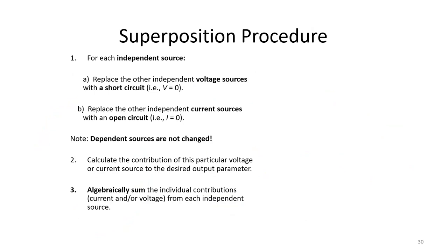Remember that the superposition procedure is actually pretty straightforward. And this is also a very convenient exam question because solving superposition problems often requires use of other tools like voltage division, node analysis, and our other DC circuit tools. So remember, what you want to do with superposition is draw the circuit with each source considered separately.